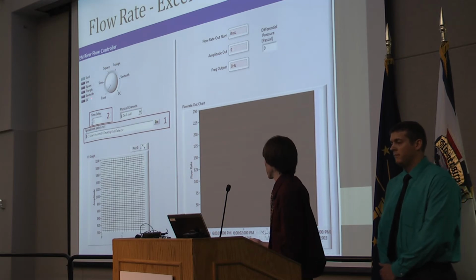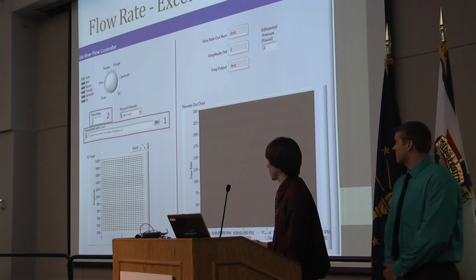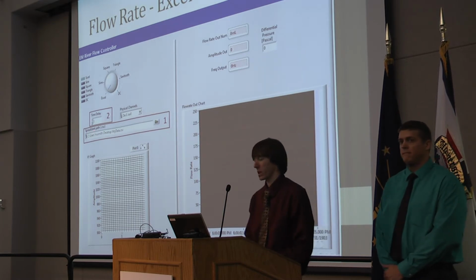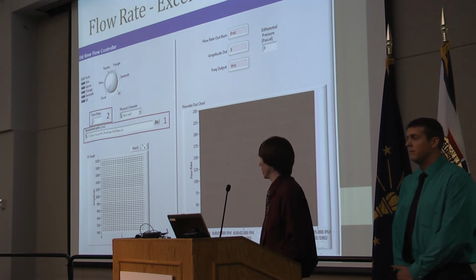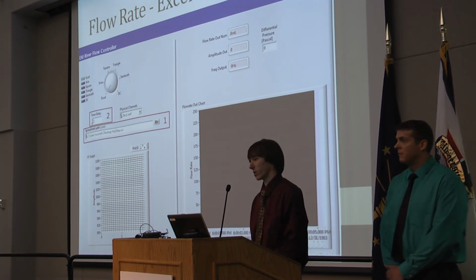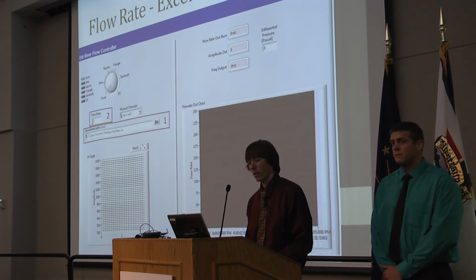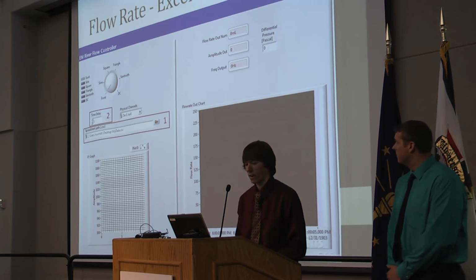The last option was Excel, and this allows the user to input an Excel file into LabVIEW so it can be read, and also change the time delay for the steps between cells. So if the user wanted to do an hour-long simulation, then they don't have to have a cell for every single second. They can do it for every half minute or minute or however often they want to do it for. And that time delay is in milliseconds right now.